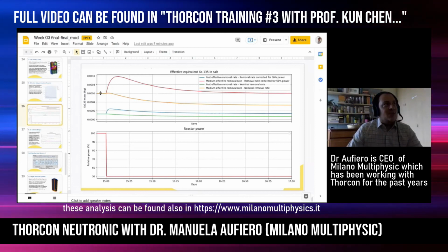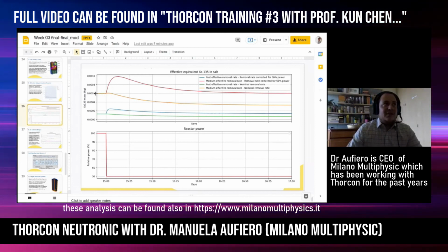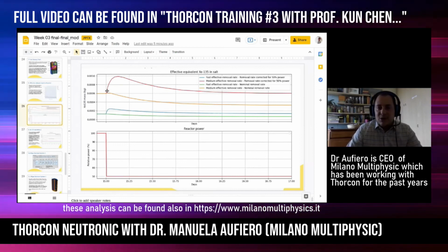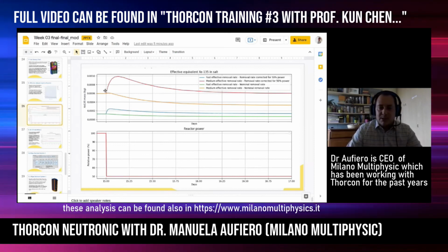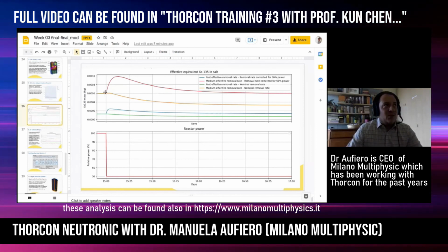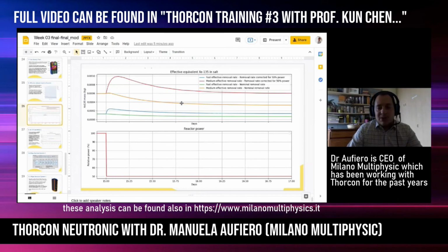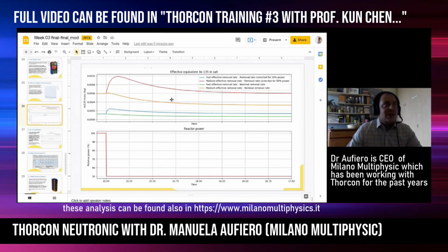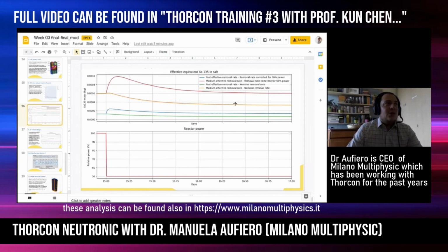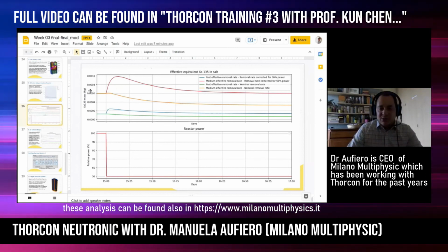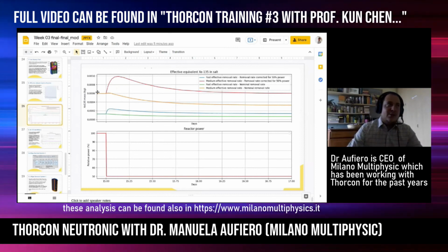So in the case where we have a medium effective removal rate, for example, meaning that a significant fraction of xenon is indeed absorbed in the graphite, if we keep removing at the same rate, well, slowly, with the time constant related to the decay of iodine into xenon, we will adapt to the new value that is roughly more or less half of the equilibrium value of the xenon concentration at nominal 100% operation.